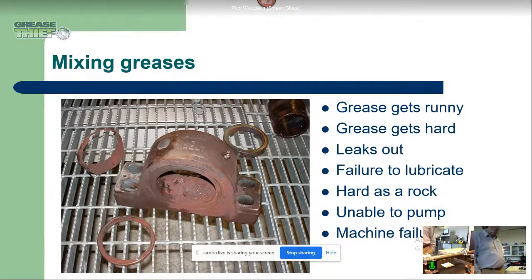And I dropped this image in here, one that I took on a job site of a critical air handling unit fan. This is how we found that bearing. Gentleman said, I think that bearing rusted out. But what we found in there with what was remaining of that bearing was some grease residue, which we were able to sample, analyze, and evaluate.